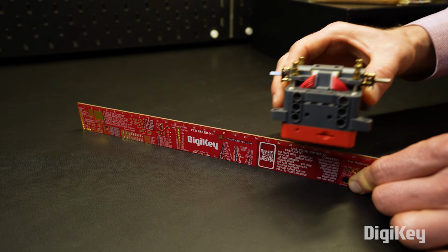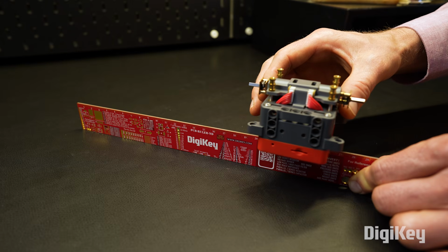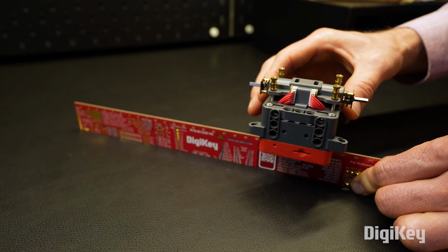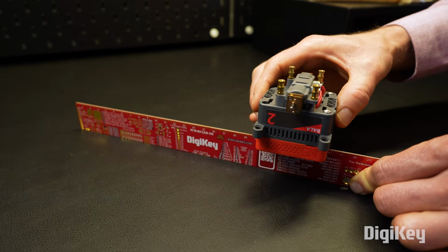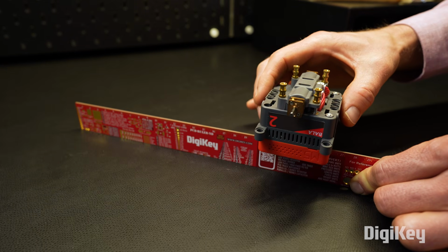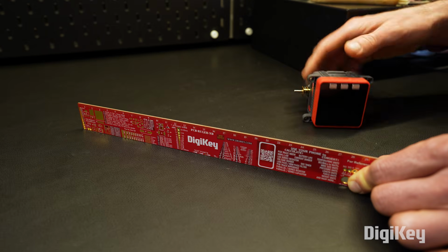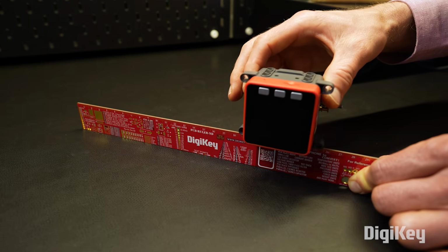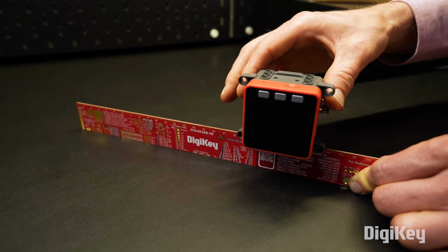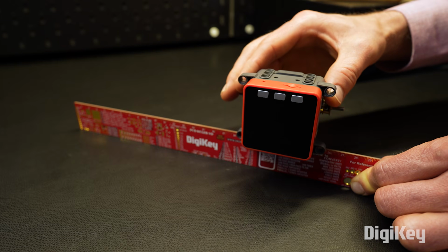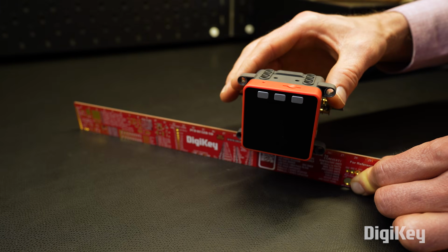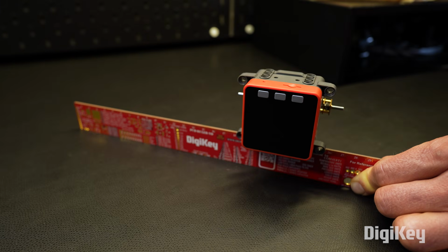We can roughly measure the center of mass for a given axis by getting the chassis to balance on a thin edge. It balances pretty well in the center of the X and Y axes, so we can assume the center of mass is in the middle of that plane. For the Z axis, see if you can balance the bot along the X axis on the front or back face. Then measure the distance from the axles. We'll assume that the center point between the axles is the origin for our 3D model.